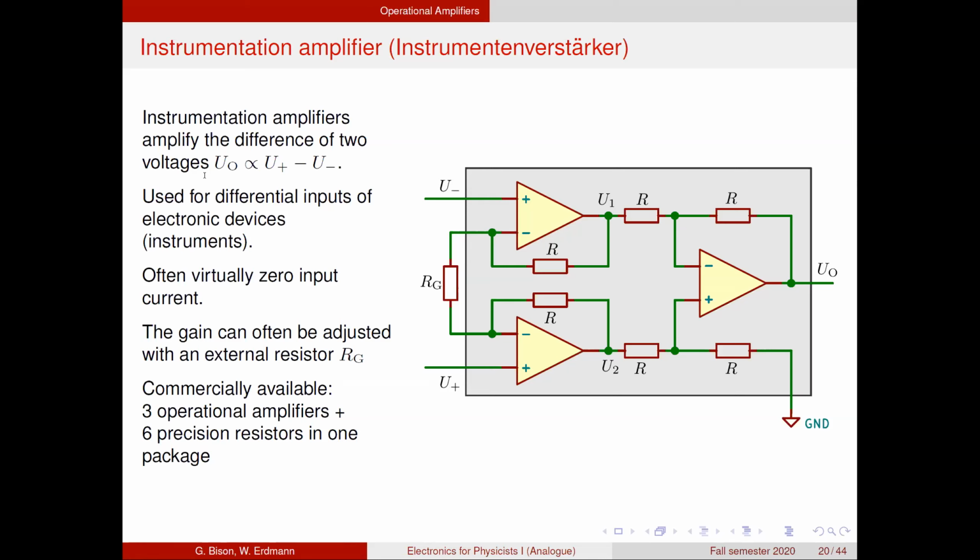And then, of course, this input voltage can be many volts. Whereas if you would directly use an operational amplifier, then this input voltage can only be microvolts. Otherwise, the operational amplifier would already saturate. So you need the resistors that you see in this schematic to somehow have the difference amplification in check, and also to have a precisely defined difference amplification.